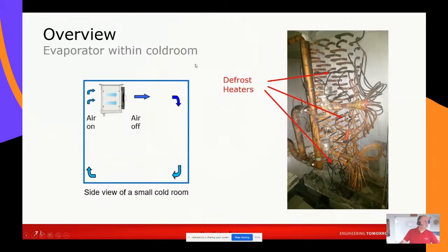That's basically an overview of an evaporator within a cold room. And here we're looking at the side of the evaporator. We've got 2 expansion valves, 2 distributors or spiders, as they're sometimes known, suction. Now, generally, if the system is short of gas, the spiders and the distributor legs will ice up quite quickly. So that's a very good visual indication of charge.